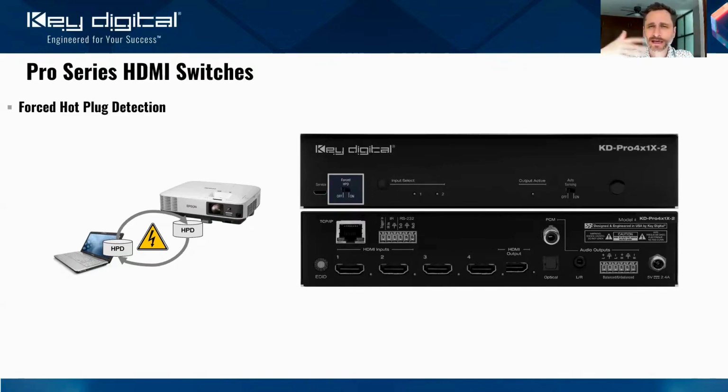Or it's what lets, I think LG is the displays where sometimes they don't even make that HDMI input a selectable source unless they have hot plug detection voltage there. And it goes backward also from the display to the source, and it happens even before the handshaking is initiated. And it's just what kicks off that entire sequence.